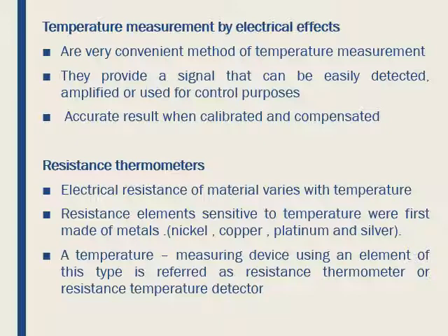Partial immersion thermometers are calibrated to read correctly when immersed to a definite depth and with the exposed portion of the stem at a definite temperature. However, they are inherently less accurate than the full immersion type. If the exposed portion is at a temperature different from that at calibration, then a correction must be applied.